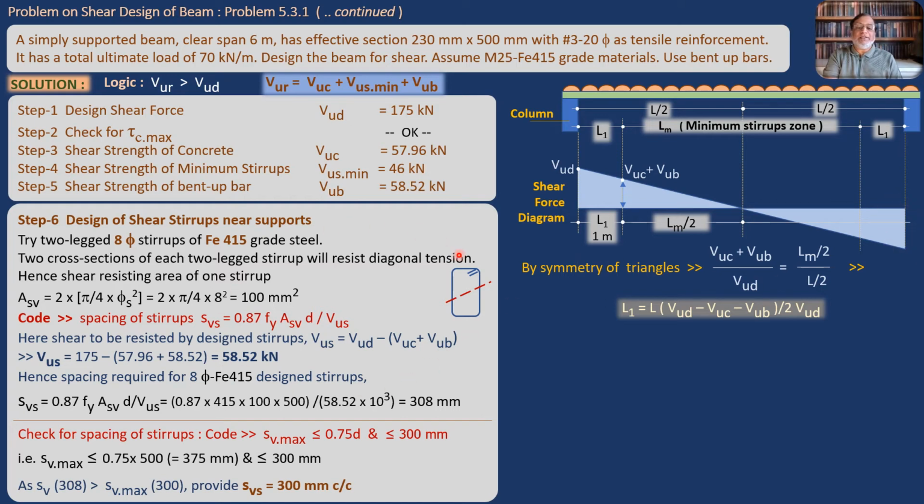What we have done in the design is we have taken this extreme value 175 and calculated these stirrups. And now we are saying that we will provide these stirrups for the entire beam. So that is actually theoretically not necessary. Wherever the critical section is, this spacing and these stirrups are necessary. So we will consider one intermediate section here. What is this section? This is the section at which these minimum stirrups will start. The minimum stirrups will be enough for the middle zone.